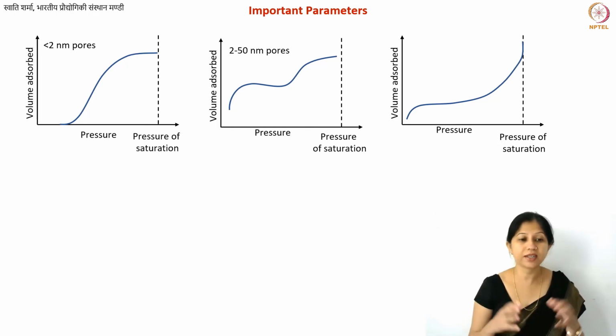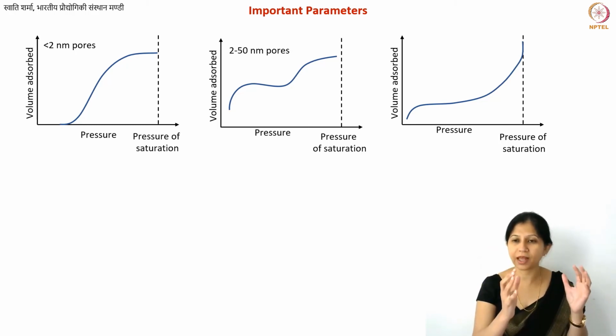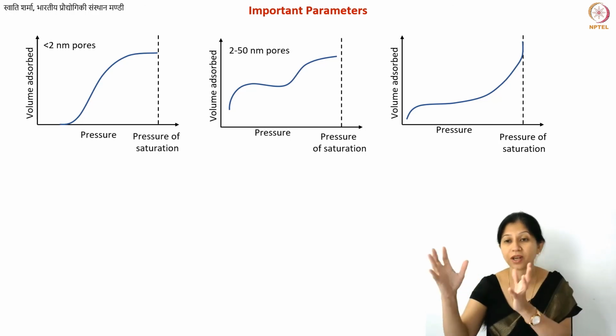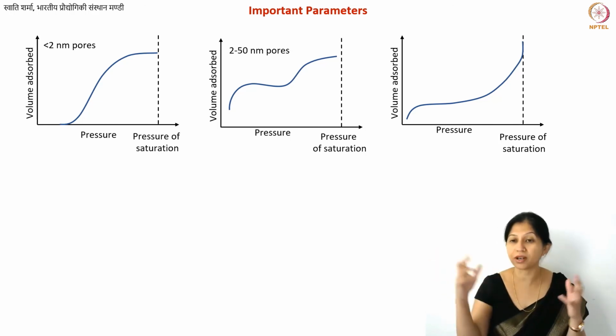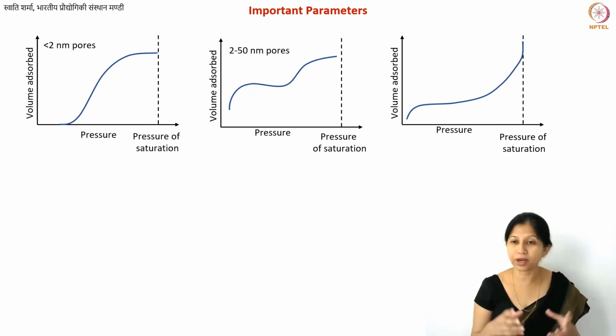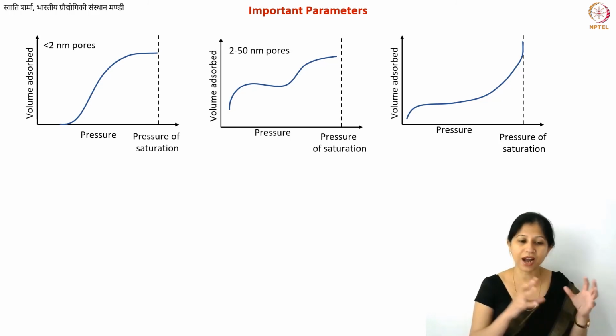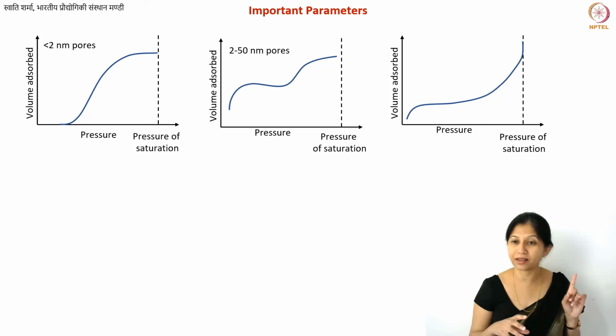Usually you'll have certain types of pores, let's say 2 to 5 nanometer or below 2 nanometer. You will have a bunch of these pores, and then nothing for some time, and then a bunch of slightly larger, let's say 30 to 50 nanometer pores, and then a bunch of macropores. You can understand this from the fractal geometries, right? So you don't have a constant, linear increase in the pore size. You rather have 3 or 4 different regions which you will get in the adsorption data.